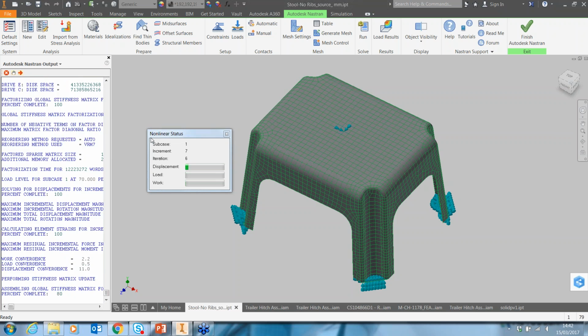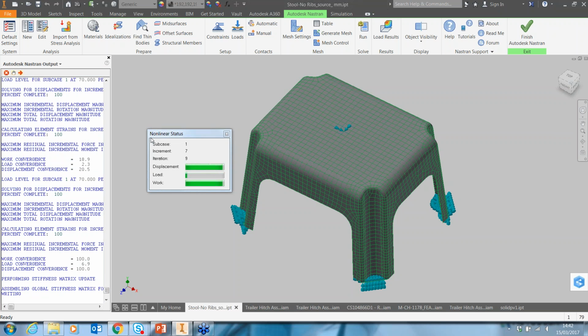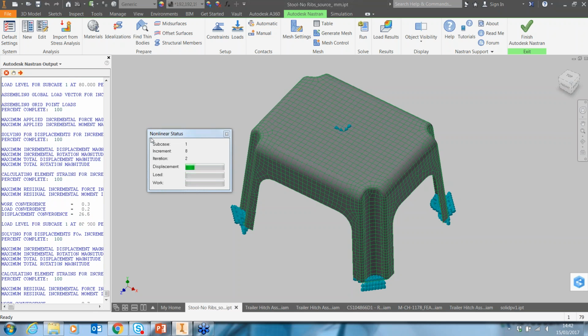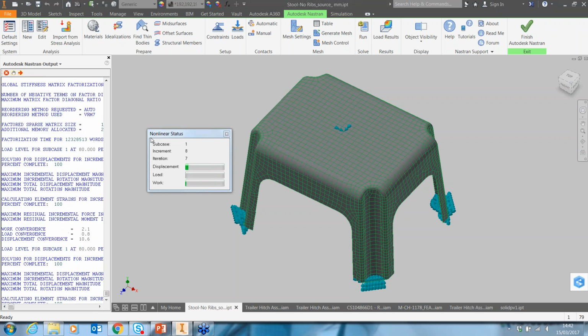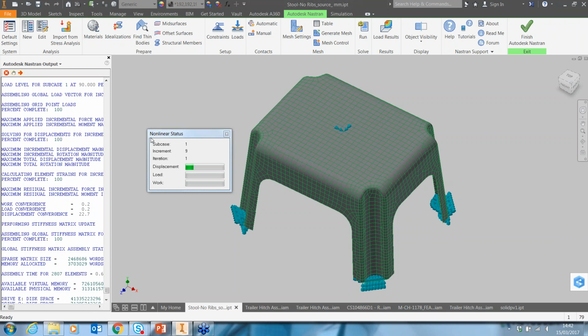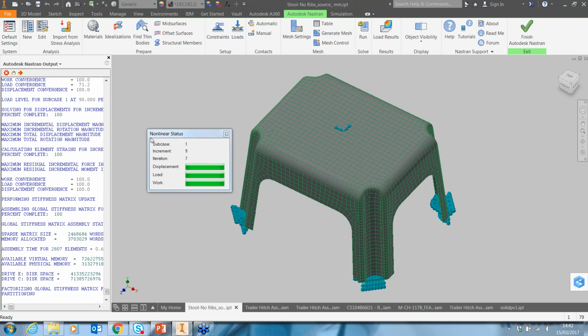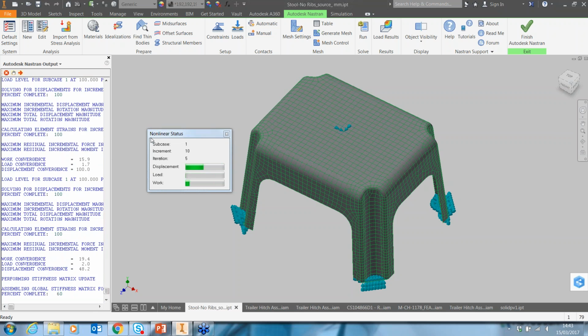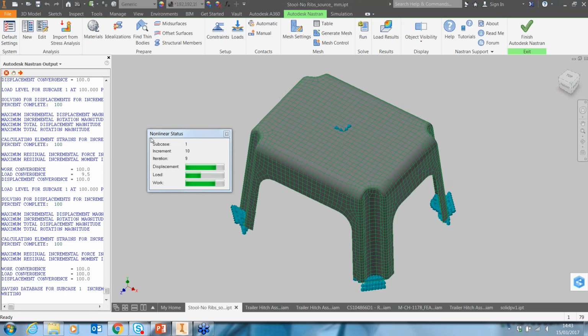If you are working in some industry, they do require that you present results to certain codes like DNV. They normally do stipulate that you use large displacement analysis. Large displacement analysis is a non-linear analysis I'm showing you now, where it applies the load in small steps.